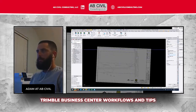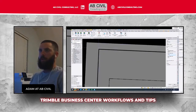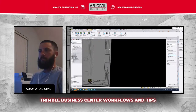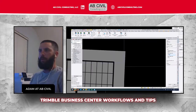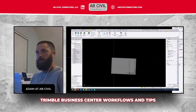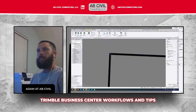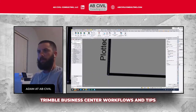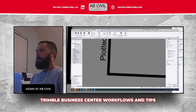So for the width, you can click twice to create a distance. I just pick the top left corner, then the full PDF top right corner. That set a width of 32.8 inches, which doesn't matter at all in this situation. Then for height, I click top left and then bottom left to get my height, which happened to be 21.2 inches, but whatever. Location is the bottom left, lower left corner. It says it right here on the screen.